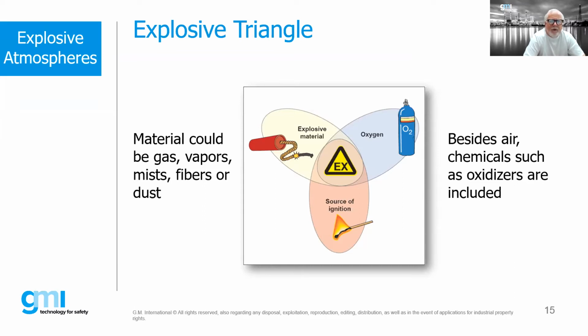If we removed oxygen completely from the environment, that makes it very difficult for people to work in an environment where there's no air. So that's usually not an effective solution. Certainly removing the explosive material is ideal if we can, but in many cases we have to put electrical equipment right in those areas in which an explosive gas, vapor, or dust is present.